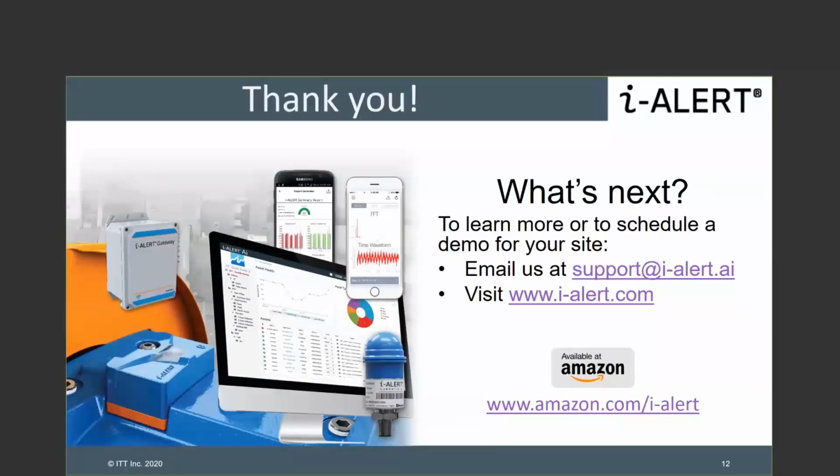Well, I'll answer the first part of that question first. The ways to install it: the iAlert can be screwed directly onto a pump. If it's a Gould pump, there's an I-frame design that allows you to put the iAlert directly in the most advantageous spot on the pump. If it's a competitor's product, and that doesn't necessarily mean a pump, it can be a blower, a fan, a compressor, et cetera, you can epoxy the iAlert onto the equipment. And the way to do that is we sell bases that go under the iAlert, and these bases are inexpensive, so you would screw the iAlert to the base and then epoxy the base onto the equipment.